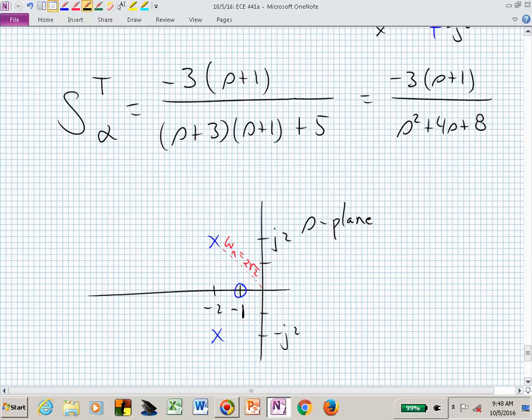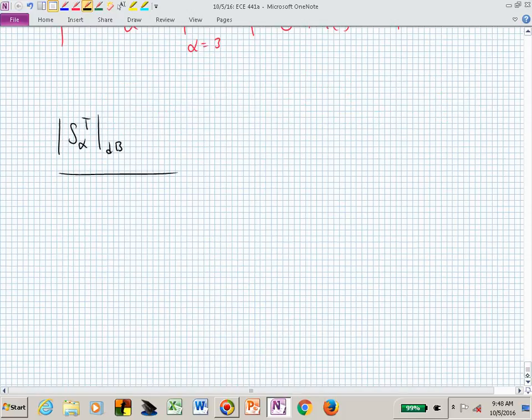What happens in our Bode plot when we hit a 0? It's upstairs, isn't it, the 0, so we're going up with our slope. And our slope, it's a single factor. So this is now at 1, and what happens? You said we go up. How could I label that slope? Plus 20 dB per decade. And do I just keep going? No. What happens?